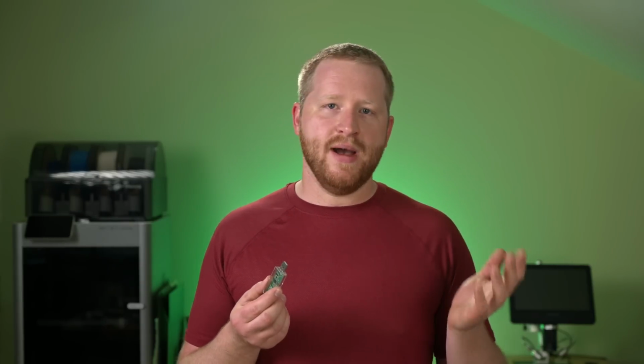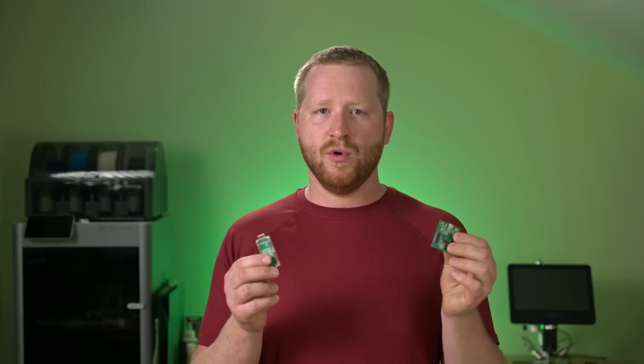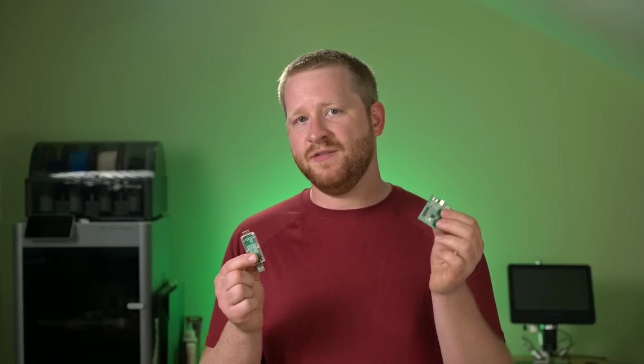I used the serial adapter built into the Link E, as well as MobaXterm on a PC. All I had to do was connect 3.3 volts from the debugger to VCC on the board, ground to ground, SWDIO to PD1, and RX to PD5.